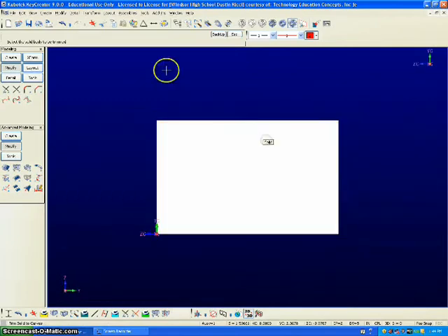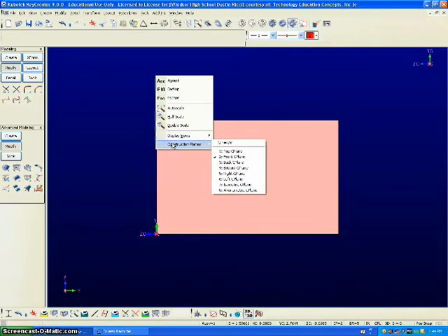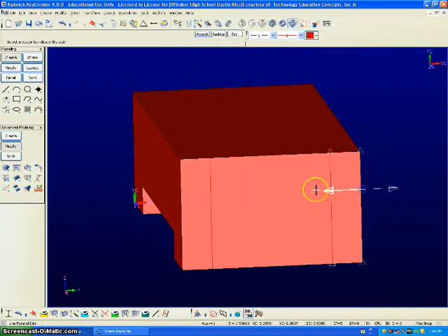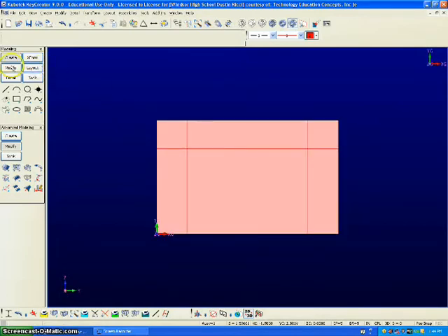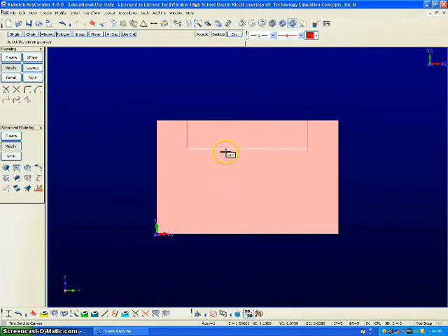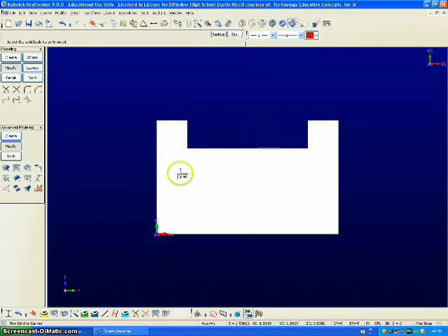Now we're going to do the same thing from the right side of the block. So make sure you have the correct display and construction views. Create line parallel distance 0.5 from the left and right side, as well as from the top. That's right view. Modify trim first. Trim these lines so it's like the ones that we just did on the front view. And trim solid curves, OK. Select the 3 trimming curves that we just trimmed. Accept, solid body, and again to your left. And that part's gone.